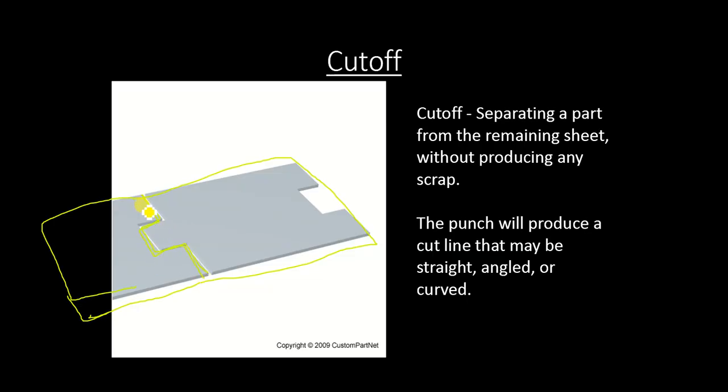And there is no scrap in this material. We are just cutting it. You can just imagine you're using a scissor and cutting paper. If you're cutting in this way, there is no scrap, right? Obviously the paper will be split into two pieces, but there is no scrap. In a similar way, we are applying the cutoff operation using a punch, and the sheet metal is divided into pieces. Here also it is punched, and you can see it is cut off, and the other material which was present in this region has been utilized for different applications.